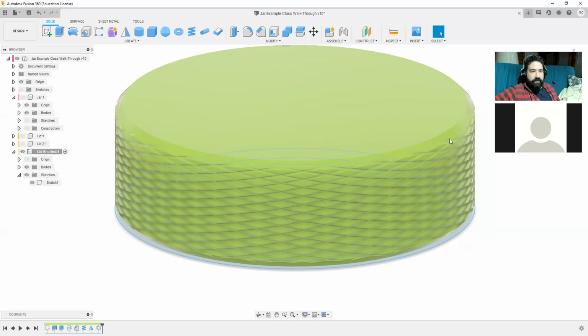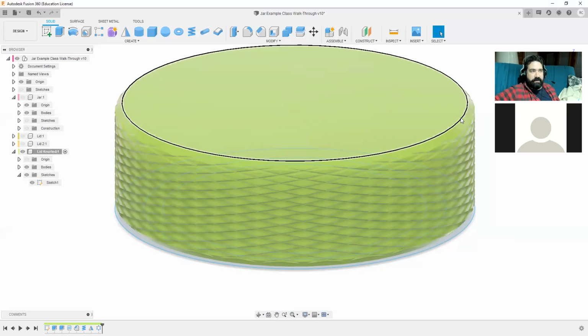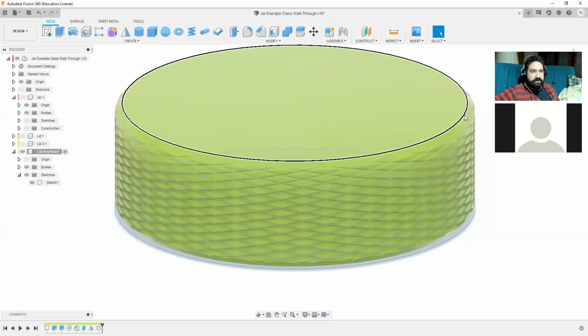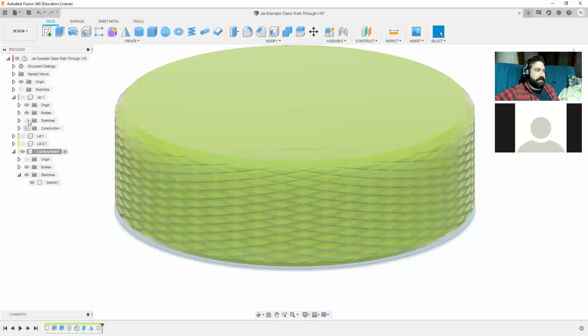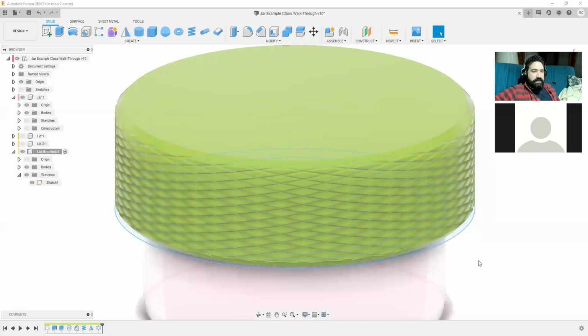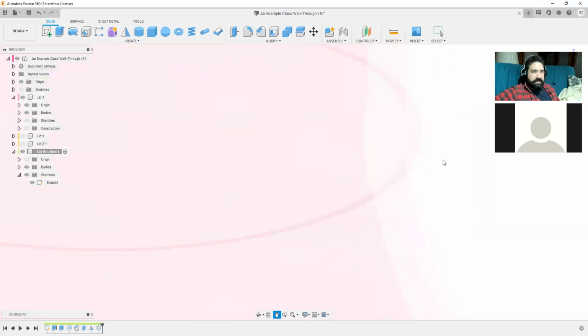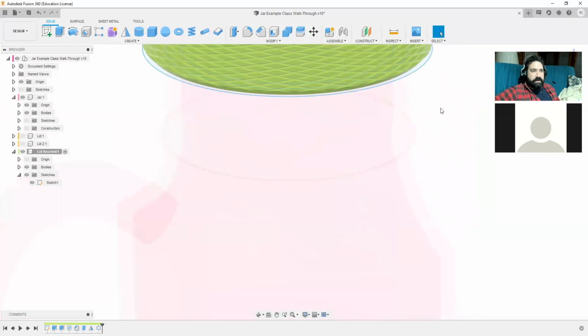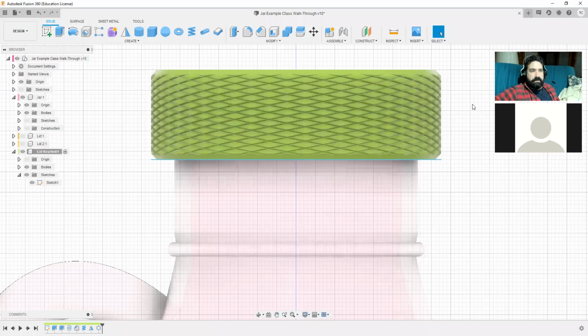It's the same thing if I had wanted this whole top here to have a circle to it or something like that, like a ridge. Well, I could maybe use the pipe tool, or this is where, like I did, and I'll unhide the jar, when I created the little half round part here, I went in from profile, sketched right on the edge, used the revolve tool and moved that around, but then joined the two together to create one solid body to create that feature.